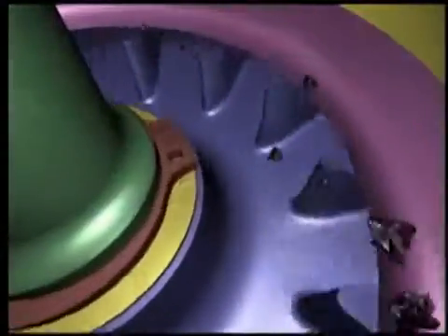Once the oil and contaminants are drawn into the rotating group of the pump, the contaminants can cause damage in several ways. The larger particles cannot pass through, but will break up as they strike the stationary port plate, shown here in yellow, and accelerate wear. Notice how the contaminants break down the edges of the port plate.